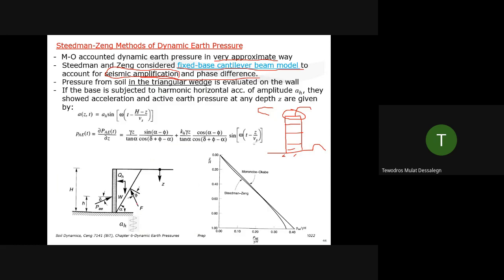The same is true for dams and retaining structures. If you have input motion here, now we are assuming the same acceleration throughout, a single value. That's not true, right? Because there can be amplification through the sway. Either we should record at this level, not at this level. The higher this retaining structure, the more approximate the solution is. Or you should somehow account for soil amplification. The same way the structure is amplified, the soil can amplify too.